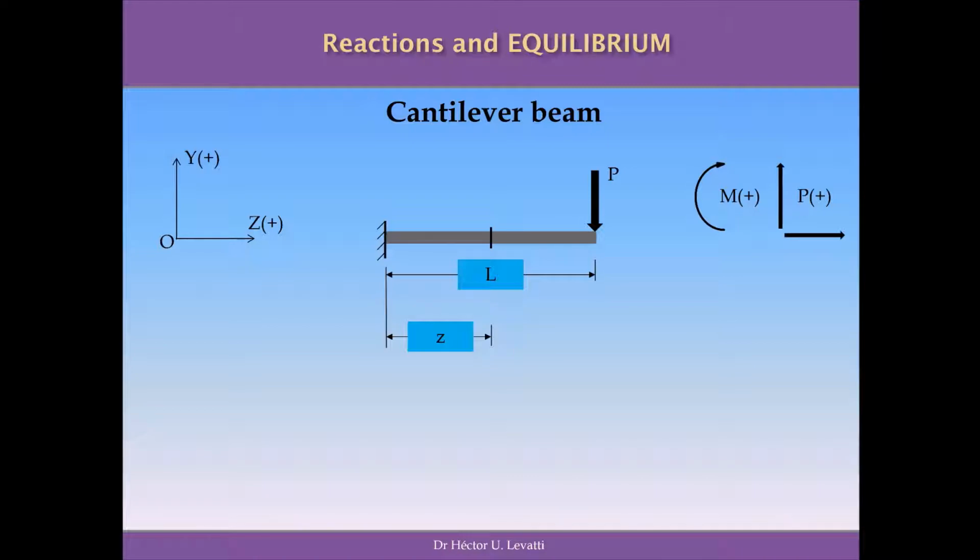So in this particular video, I want to share with you concepts around the functions that describe the distribution of bending moments and shear forces. As I mentioned in the previous videos, these bending moment diagrams and shear force diagrams are in reality functions in a two-dimensional space that describe the variation, cross-section by cross-section, of the bending moments, shear forces and axial forces in a beam or in general in any structure in civil engineering.